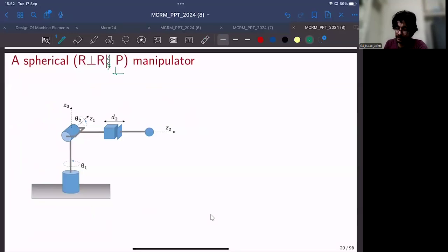So in assigning this DH method, first you assign the Z-axis frames of reference. So the ground frame will have, the first joint will have Z1 pointing vertically upward. The second frame will have the frame of reference pointing along this direction or this direction.